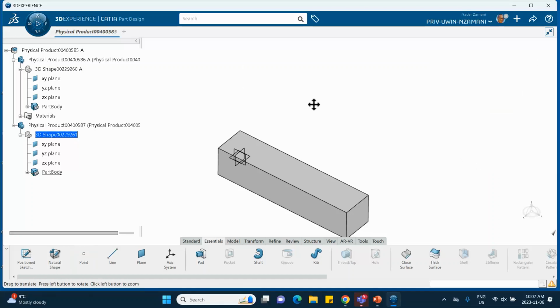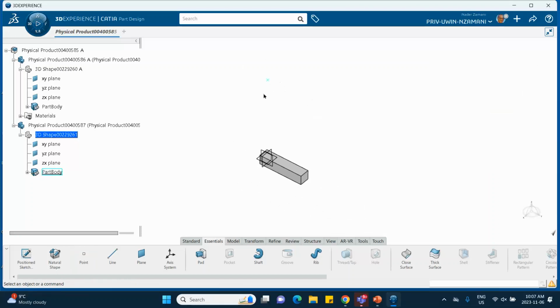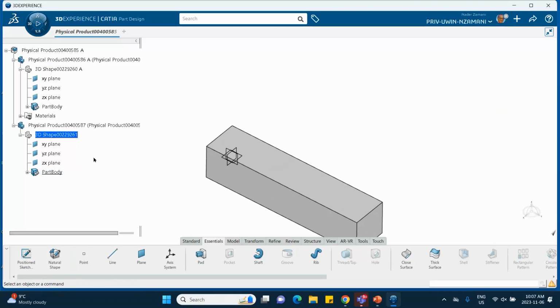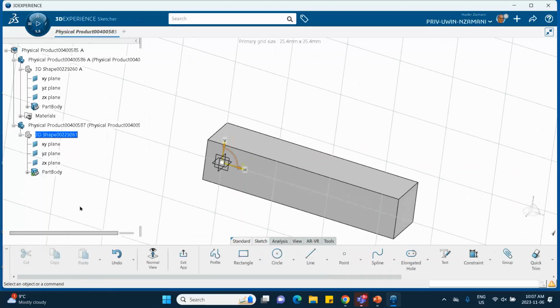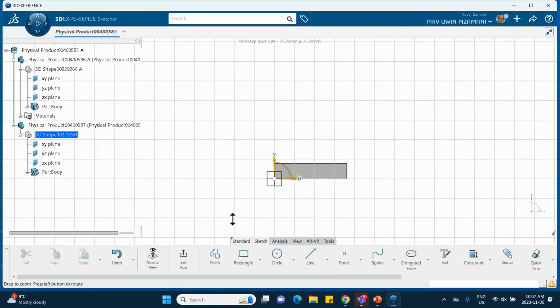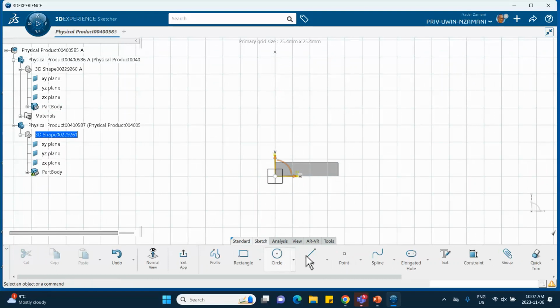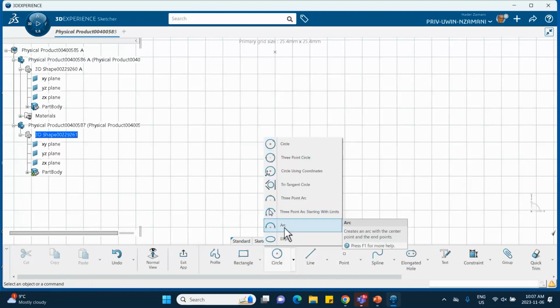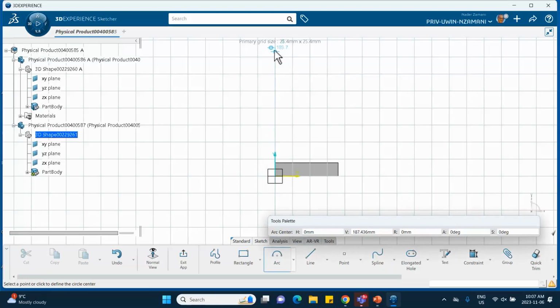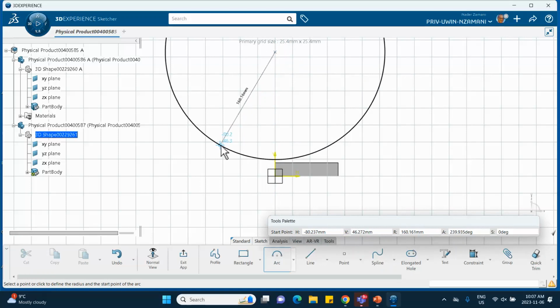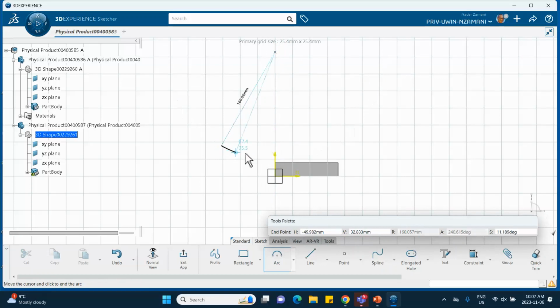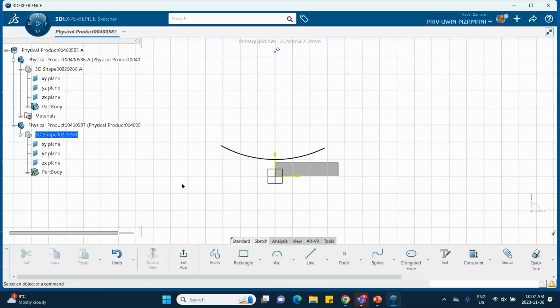Okay, so it's right there. This is the reference point. Now, in that same plane, which is that plane, I will sketch the arc, which eventually becomes part of the drum. Okay, so the pressing drum. So let me do an arc. The center is right here, and then I don't have to model the entire circle. It's not necessary because during the time that we're looking at, this does not make one full revolution anyways.